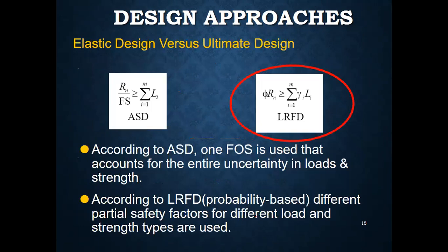The factor of safety in this design ranges from 1.5 to 2, while the other theory that we have is the ultimate design theory. If we look at the stress strain curve of the steel, the elastic design theory is based on the range till the yield point of the steel, where Hooke's law is followed. Once the necking is produced in the steel, we have the strain hardening stage.